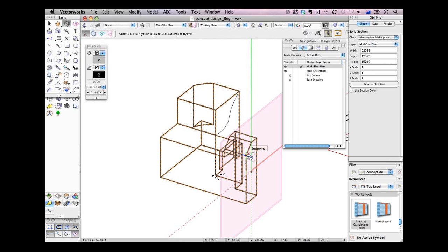You don't need Landmark for a site model. You can use Architect to create a site model. But there are several things you can use with Vectorworks to create a site model. 3D locus points, you can use 3D polygons, you can use 2D polygons and convert them. So there are lots of choices. If Google Earth will give you 3D polygons, then yes, you can.